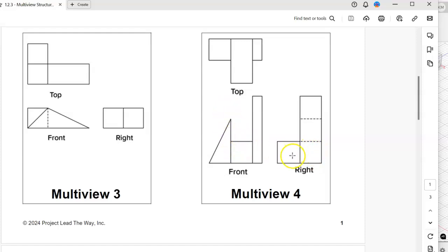And that would make sense as I look at my right view. I've got this long object that's obstructing all the edges. So I've got a hidden edge here, which represents the peak of my triangle right there, as well as this hidden edge, which represents the top of this rectangular prism that we've got down the bottom. And that's this projecting this line over, and that's what I see there. And it turns to solid because this is only half of the depth as we look at the top view. Let's see, I'm seeing this is an object line, what would be right here coming out to here, but this portion would be hidden as well as this portion, which is represented by the top of my triangle. So I think we're going to have to do this in just 3 separate sketches.